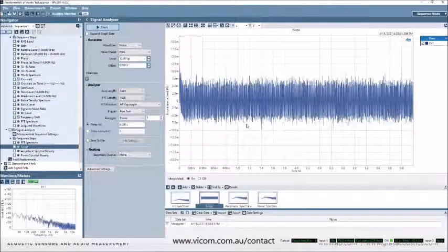The improvement that's been made since then is that mathematically, if you sweep continuously but accelerate at an exponential rate, there are some very interesting things that happen when you do the mathematical transform that allow you to extract the THD data. So yes, the log part in log chirp refers to the fact that it's an exponentially increasing rate of change in the frequency with time.